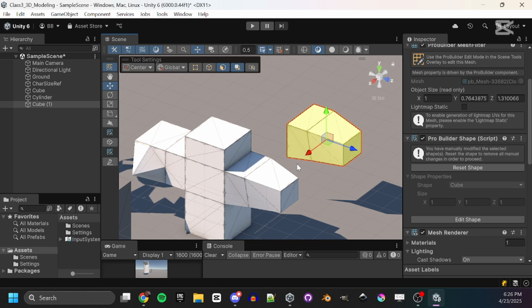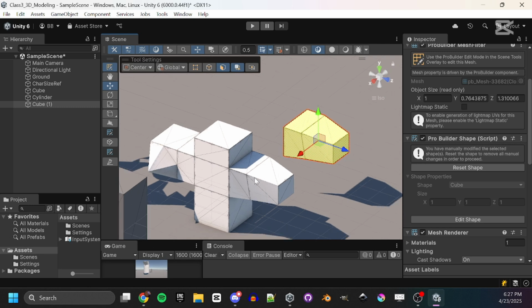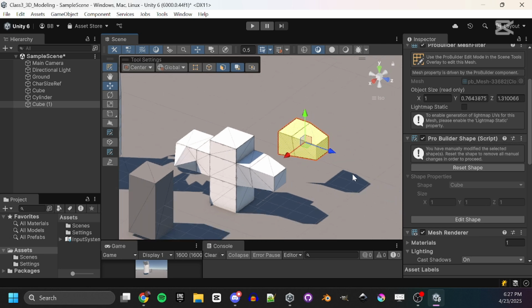But you can make something that looks identical, but instead of the lines running as you'd hope they would, they're running a different way. It makes the same shape, but when you try to bend that, those edges don't bend nicely, and you get pieces poking out all over the place. So just know, in the beginning, don't worry about topology, but eventually it's going to matter. You're going to start to care about where I actually put things.